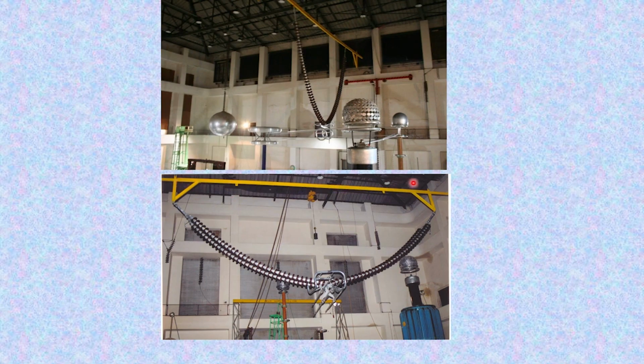This bar is like a tower, where from tower to tower the insulator strings are connected with the necessary hardware. This is again a corona control ring arrangement for the double suspension V string. So, with the conductors, which are 4 in number as in the field, the simulation has been done, and then the voltage distribution will be measured across each disc. This is the line end, which is connected to a 1 million volt transformer here. From here we apply the voltage and see the breakdown up to the ground level, and estimation is done.